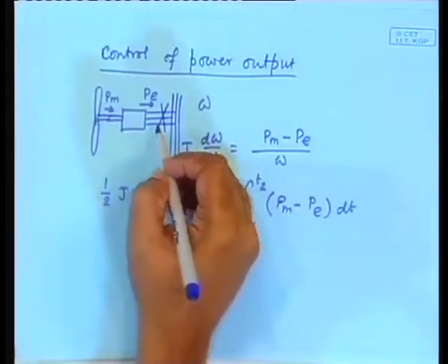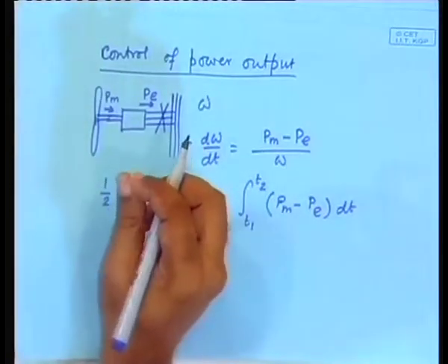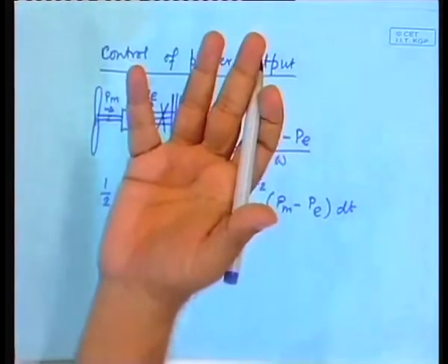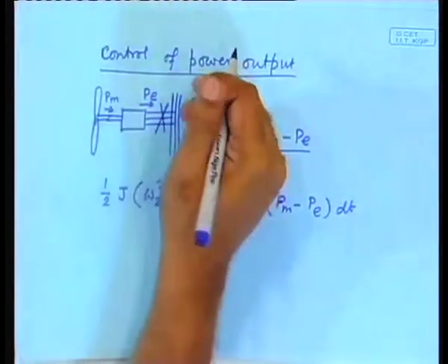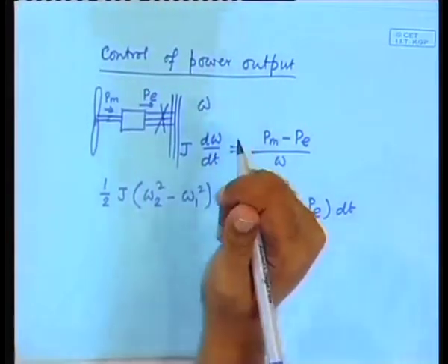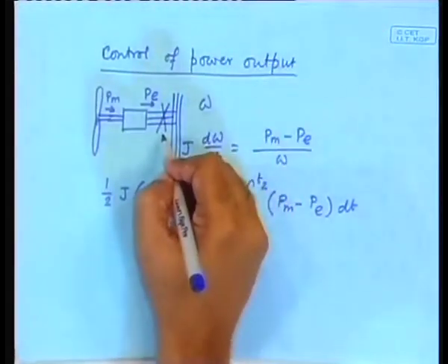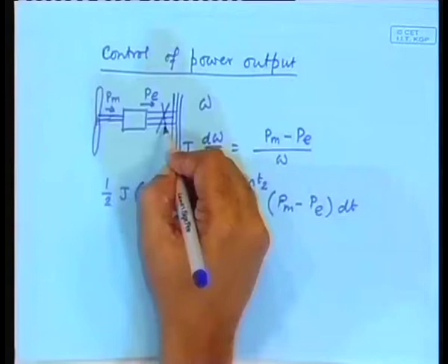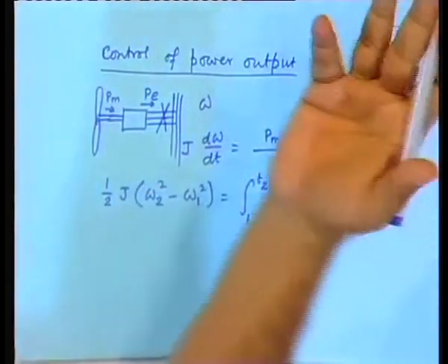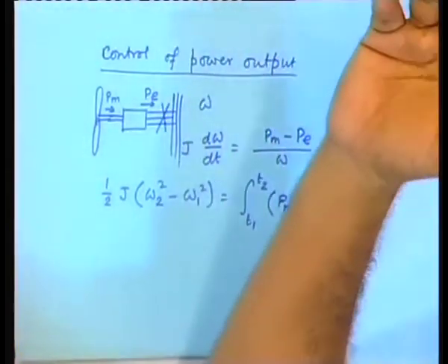So there has to be a protection mechanism, so that if the speed of rotation goes beyond a certain value, then the braking mechanism must spring into action and stop it, because these are not uncommon. Breakages of the electrical line are not uncommon. You have seen that even though you have a reasonably secure power supply, you do have load sheddings. Similar things can happen here. If this line does not have power, you are gone. So, these are other control strategies you need to have. Clear?